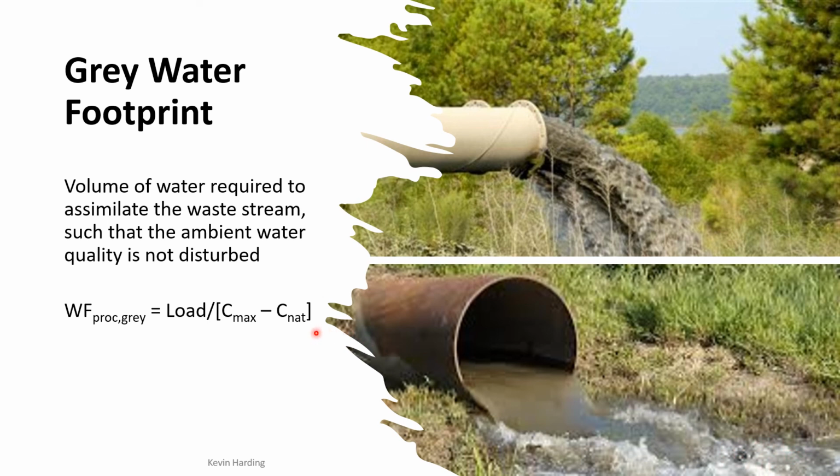If I have to take a 100% clean stream of water, so there's zero pollutants in that water, I have to mix it with my dirty water, and then from a mass balance from those two streams, I then end up with a stream that has the same concentration in our river. So our river is obviously going to have some pollutant. It's never going to be 100% clean. We are using an assumed 100% zero pollutant water stream that I'm now adding here to the left of this.